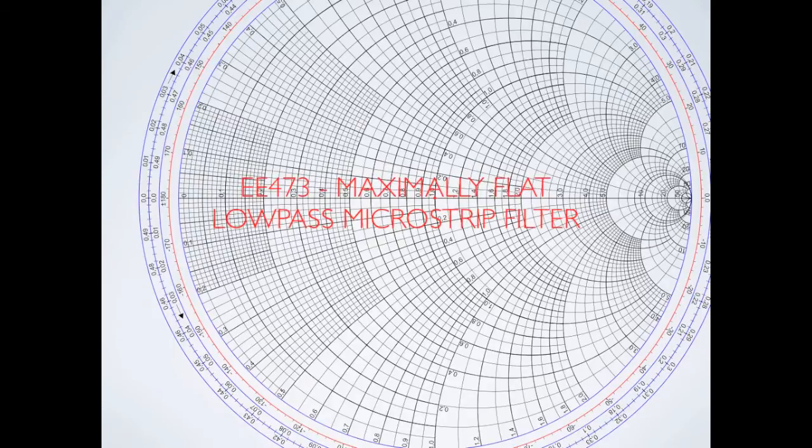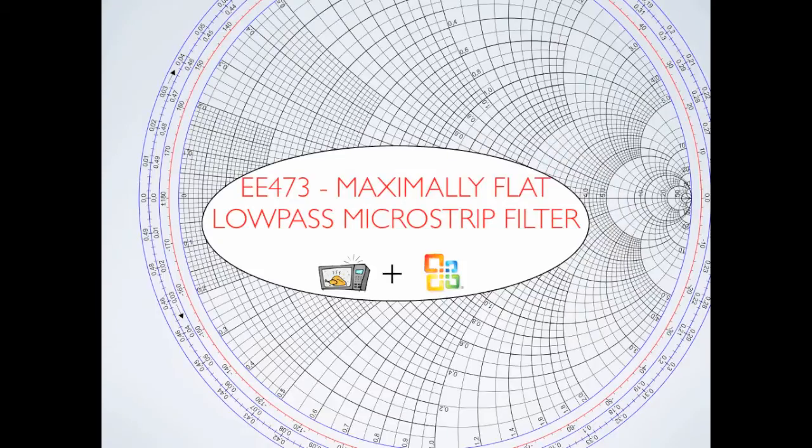And what we're going to talk about today is our maximally flat low-pass microstrip filter. We start with the design specification of the filter. Here we see that the cutoff frequency should be 4 GHz since that is a requirement for this assignment. We also set up this filter design to be maximally flat during its passband. We choose 7 GHz as our working frequency to have 20 dB attenuation at this frequency.